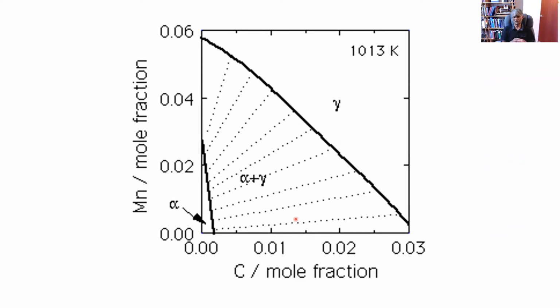And of course, all the wonderful work that has been done in the past, producing things like CALPHAD, Thermo-Calc, MTDATA, FactSage, and so on, allow you to calculate these tie lines for most of the systems that we are interested in. And if there are others which we do not have access to, then presumably some sort of work can be done to generate the thermodynamic data necessary.